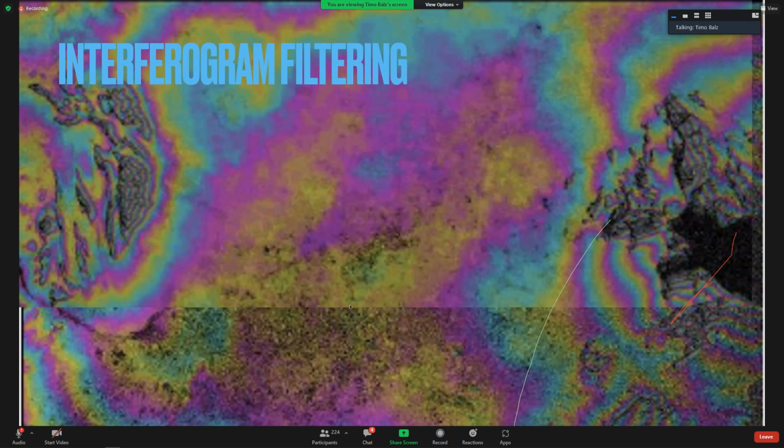and that is because people have developed special filters, especially for phase. So there are filters available. The standard would be the so-called Goldstein filter, which is optimized for phases, and it provides relatively good filtering results. So it is also advisable for many applications to actually use it to improve your phase quality, not only by multi-looking, but also by interferogram filtering.